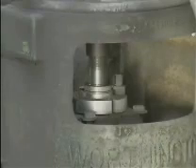When this block travels from a starting point between two extreme positions and back to the starting point, it has completed one cycle. When an object vibrates, the velocity of the vibration changes constantly. When this block moves past the center position, it's traveling faster than it is when it reaches one of the extreme positions. Because the velocity of a vibrating object is constantly changing, the highest velocity measurement is generally used or displayed. This velocity is known as the peak velocity.